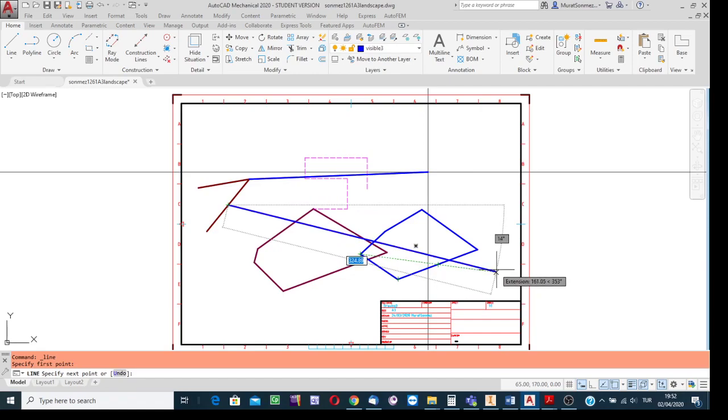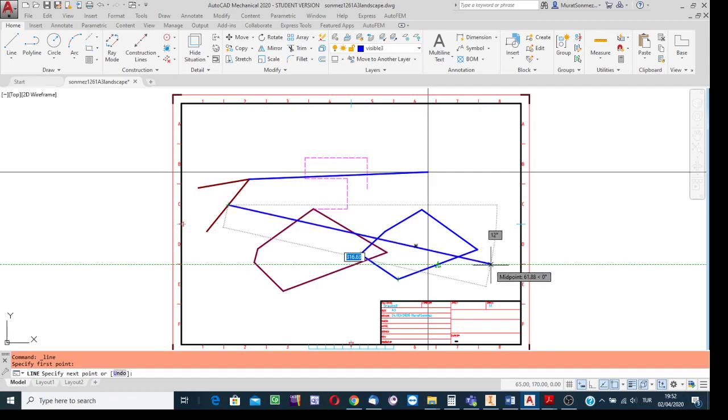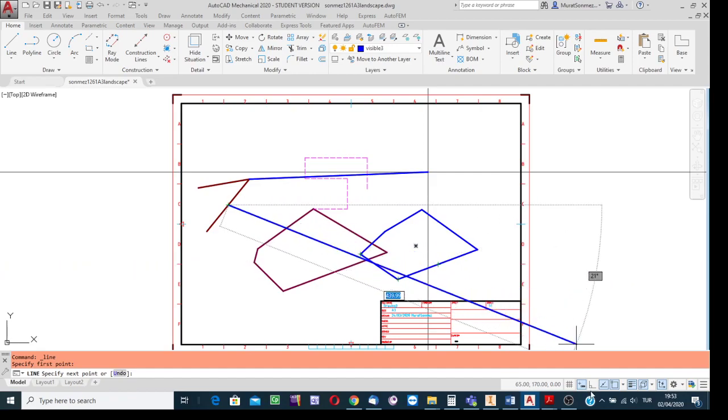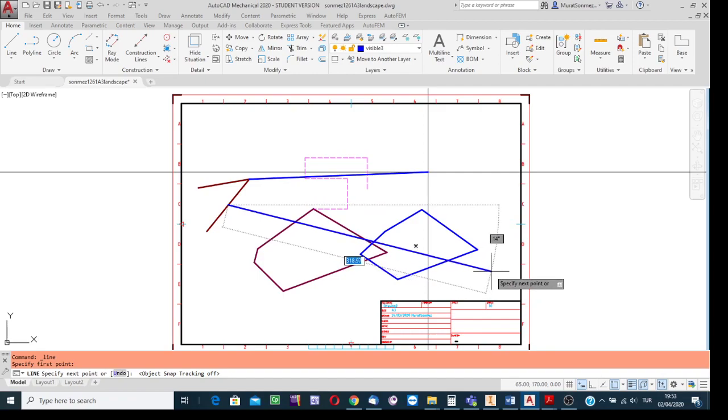Have such a further extension. Well, I don't know the length, but say after moving the cursor further away from the boundary, let me toggle off the track facility. I don't want to see track lines. For having such a further extension, in the first box, which is now highlighted, write a number for the length of this line with its further extension.